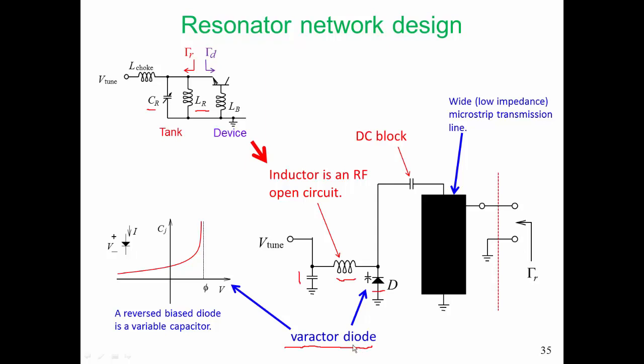That's the main characteristic. The capacitance of the Varactor diode will vary with the voltage across it, and eventually that capacitance becomes very large, at what is called the built-in potential. We usually only bias the Varactor diode in that negative region, because in this positive region the capacitance is changing very quickly.